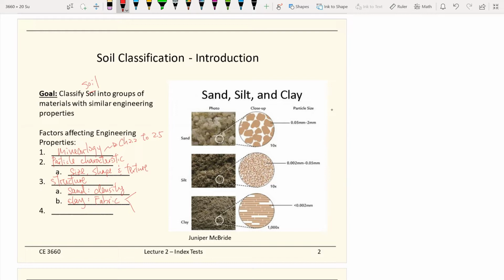But there are two different types of fabrics of clay: the dispersed one, or the flocculated one. For the dispersed clay fabric, you could think of a bunch of cards stacking on top of each other, because the clay particles, down to the element level, are like sheet type particles. So it becomes a matter of how to organize the cards. You make up the fabric of the clay.